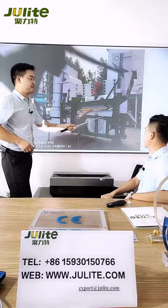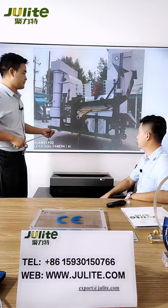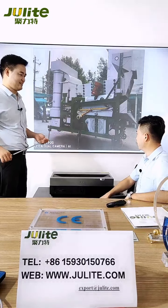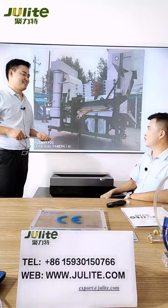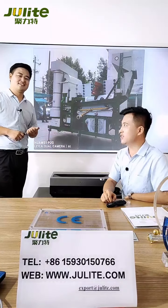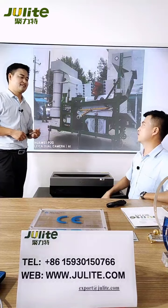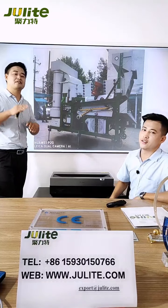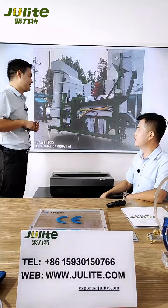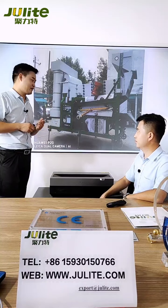And here you can see there's an exit. Yeah, exit. And also there is a fan. What is the function of this fan? This fan is the same as on the machine, the 25S, we have introduced. The fan has the same function, to blow air to the tables. Its function is to make the materials on the gravity table separate, right? And with the vibration, then we can get what we want from the materials.